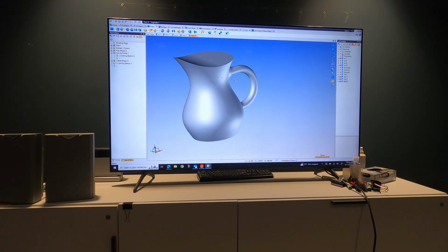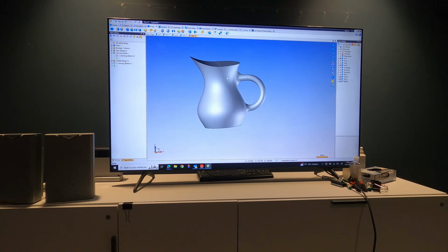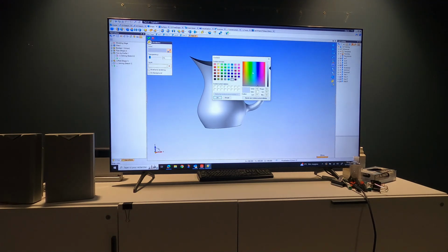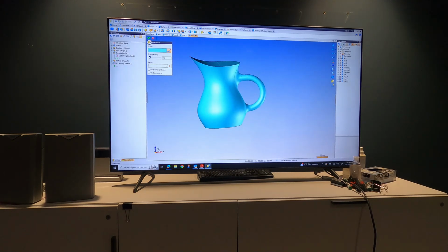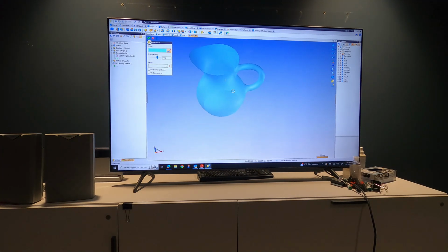Now you right click, change the attribute. Right click here, attribute. Select the color. No, not this one. Light blue, something light blue, yes. Okay, accept this, and now you play with the transparency, like 80 or 70%. Accept this value. Do not create machine document.